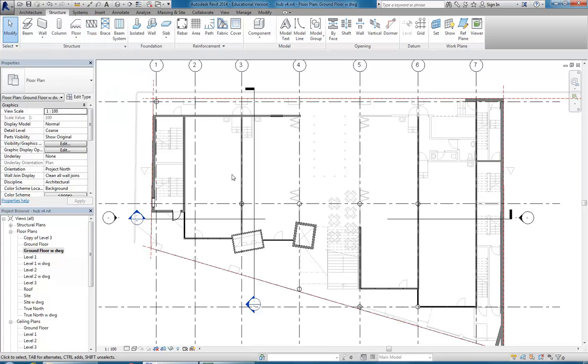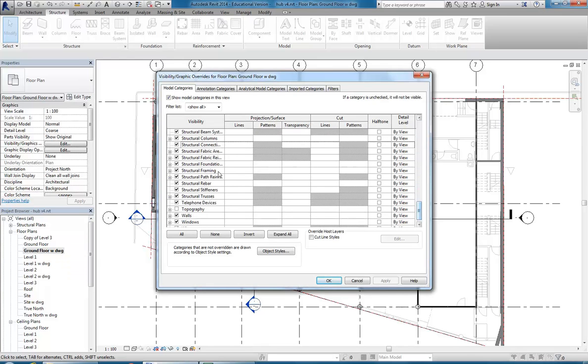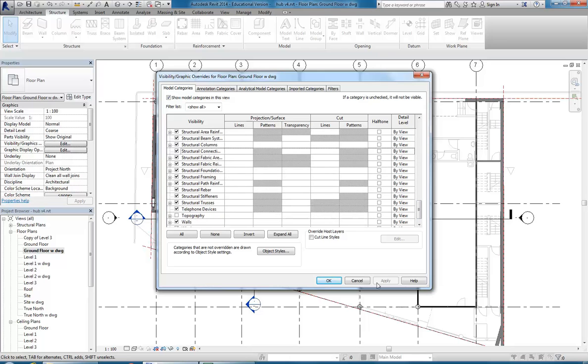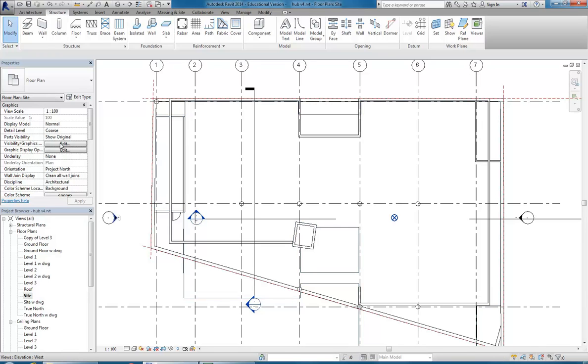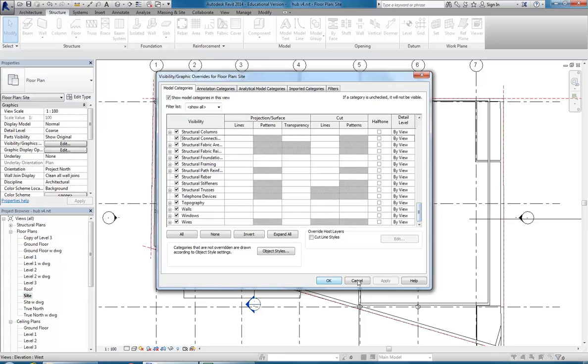And so the main issue with structural elements though is they won't show by default. So check your view settings. If you go into here, visibility graphics, edit, and then go down in the list there, you'll see that by default they'll often be turned off. Here they're turned on. Oh no, I must have turned mine on. But let's have a look in this view. I know they're on there as well.